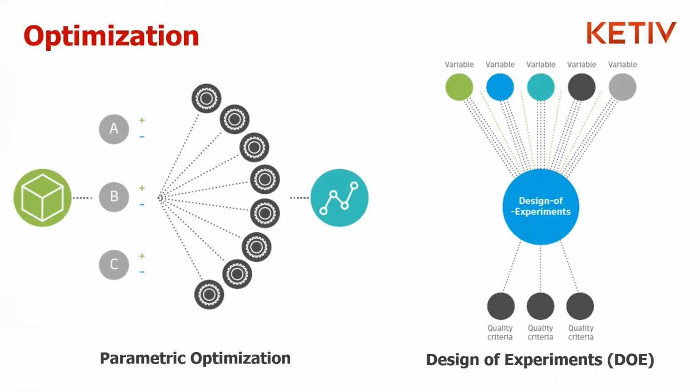Design of experiments focuses mainly on the process variables and the process settings. So what it does is automatically, with the process settings, you don't really have a baseline. You've got multiple baselines for multiple individual parameters and individual settings. You've got your baseline mold geometry and the part geometry, but all your other characteristics: mold temperature, melt temperature, injection pressure, etc. All of these different criteria can be taken into consideration for this design of experiments, and you will ultimately have multiple results giving you multiple different quality criteria, or multiple different metrics of quality criteria, which you'll ultimately be able to choose from. But the bottom line is, you're starting with a design of experiments.